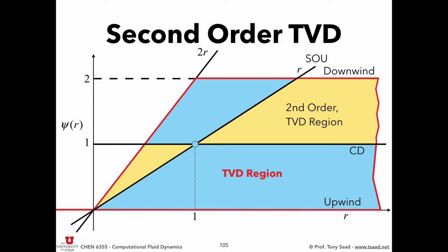So we started with looking at the second-order schemes and the K scheme. We wrote that as the sum of an upwind flux, whose leading error is a diffusive flux, plus an anti-diffusive flux. And if you leave things untouched, the anti-diffusive flux is going to destroy that diffusive flux, or leave some of it, but it's going to leave a significant dispersion error in the modified equation, which is going to cause oscillations, okay?